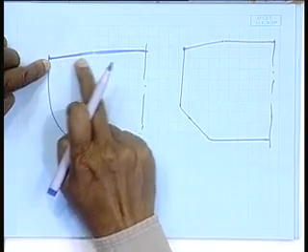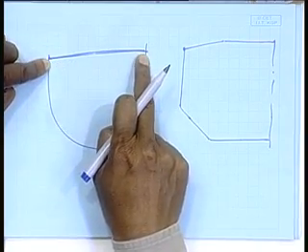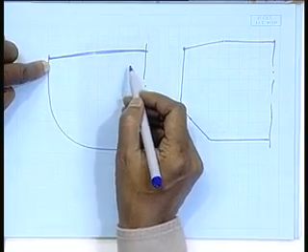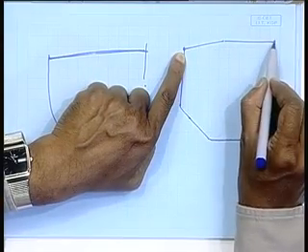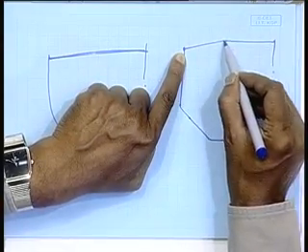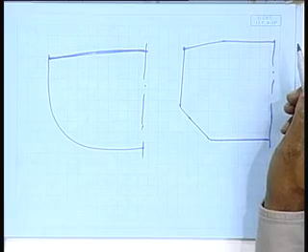The deck, I can give a nice parabolic shape to provide for the necessary camber, or I give an inclined plate with a horizontal plate welded here. So altogether the bending or making curved plates is eliminated. But well, these are one of the examples, but this may not be feasible always, because switching from here to here, this design,